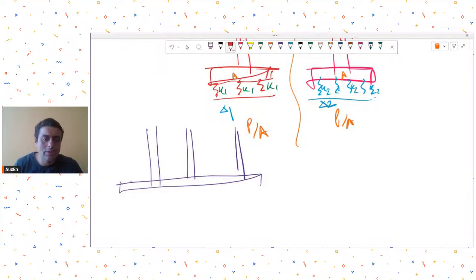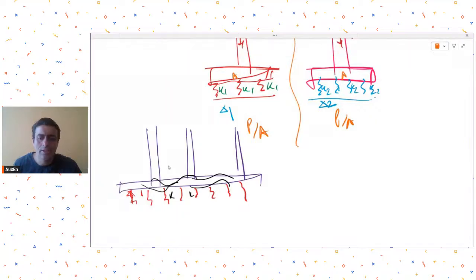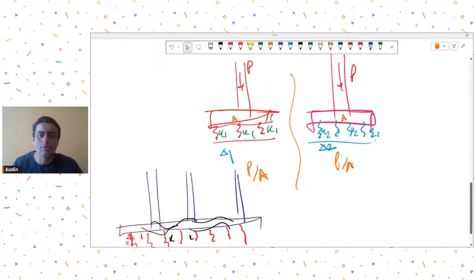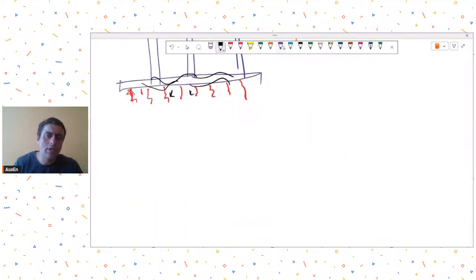Because now this is an indeterminate system, and if I put spring stiffnesses over here, because this is an indeterminate system, the spring stiffness may affect your settlement, and that settlement may cause some changes in base pressures. So when it is a case of isolated foundation, there will be no change whatever K you put. But if it's a case of raft or combined foundations, there is a possibility that base pressures may show some differences when your spring stiffness K changes.